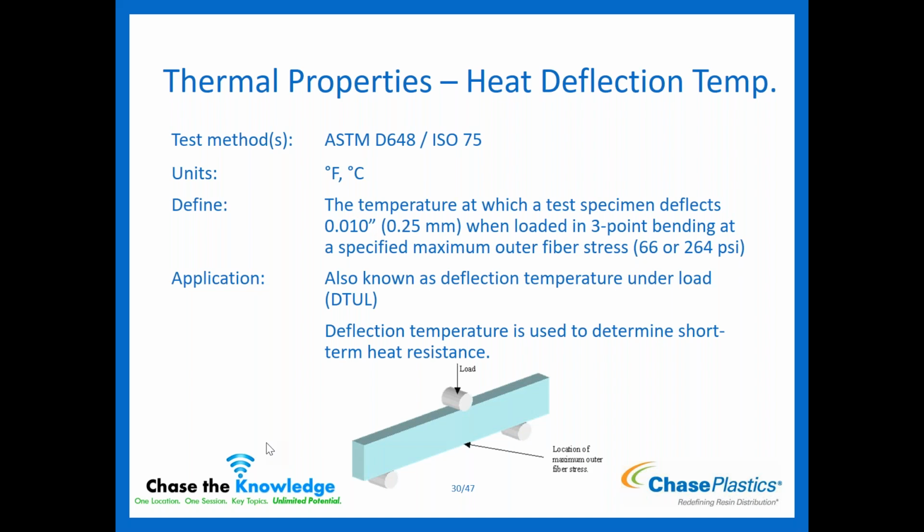If I'm looking at something above it, for instance your Ultem 1000, the HDT on this particular grade is either 201 C if you're looking at the 1.8 MPa value, or 210 C. So if I'm looking at something where it's going to be under a little bit of load, maybe a little bit of impact, at 250 C, I'm going to say this Ultem grade is no good for that. It's not going to withstand that. It's not going to be able to handle that temperature.